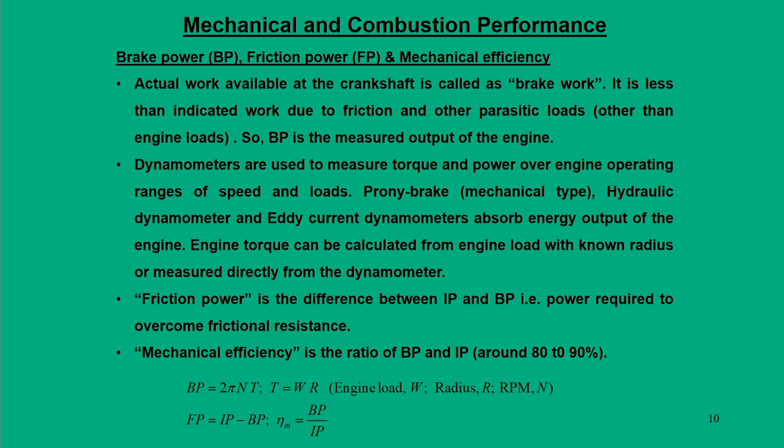When we see the indicated power, it is at the engine input side. Now, from the engine output side, that means the engine can be run with no load or with load. So, when we actually apply a load onto the engine, then basically we are braking the engine, and we interpret that as brake power.